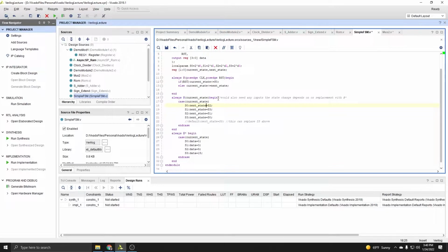So just remember, anything at a clock edge that requires an edge change and should only happen at that edge needs to be non-blocking, so that everything transfers simultaneously and one change prior to that does not alter that assignment. And anything combinational, because it depends on the previous stages of that combinational logic, needs to be blocking to allow it to get the value of that previous stage, or else your combinational logic, if you did non-blocking, would output the wrong values.